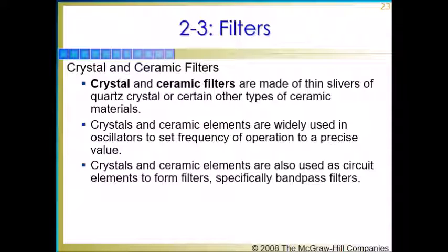The equivalent circuit of a crystal or ceramic device is a tuned circuit with a Q of 10,000 to 1 million, permitting highly selective filters to be built.